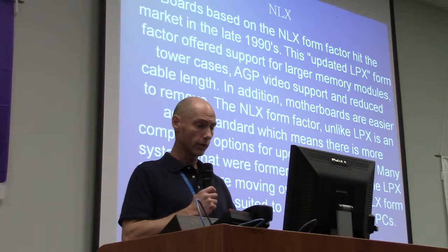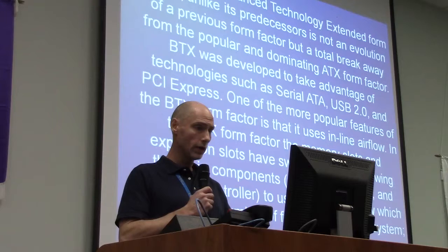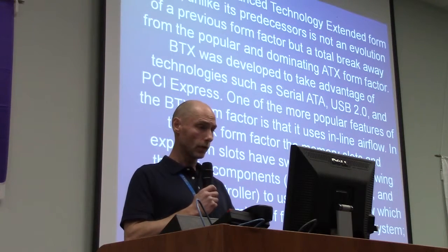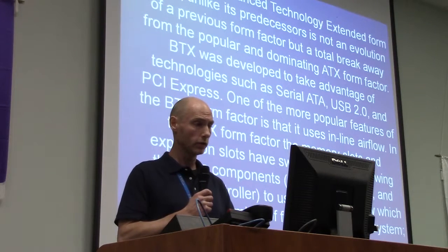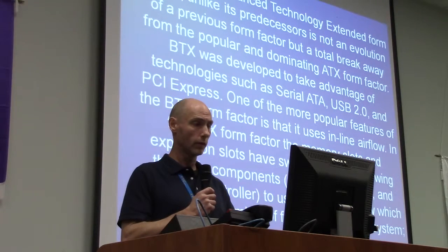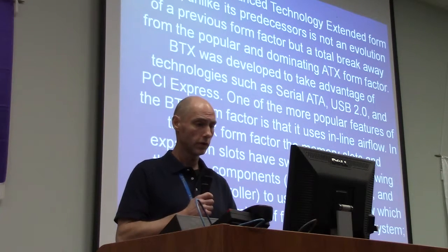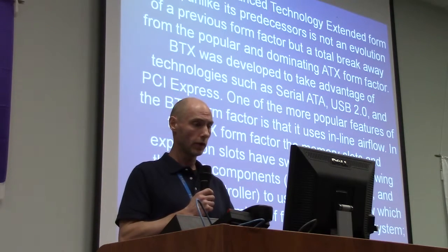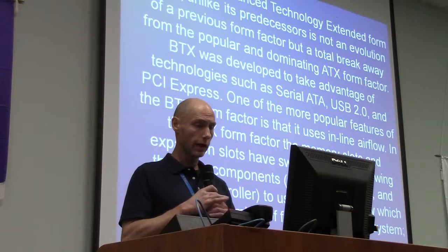The NLX form factor is well suited to mass market retail PCs. And then we have the BTX, or the Balanced Technology Extended form factor. Unlike its predecessor, it is not an evolution of a previous form factor, but a total breakaway from the popular and dominating ATX form factor. BTX was developed to take advantage of technologies such as serial ATA, USB 2.0, and PCI Express.